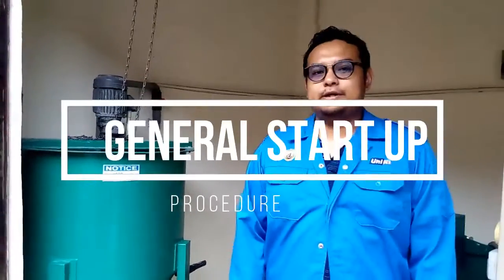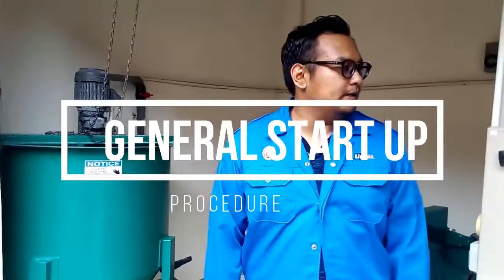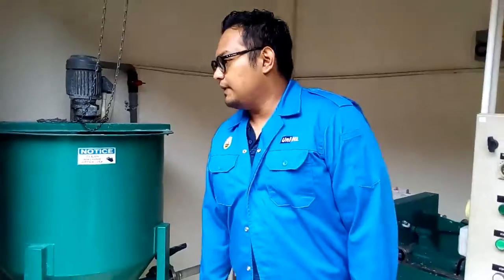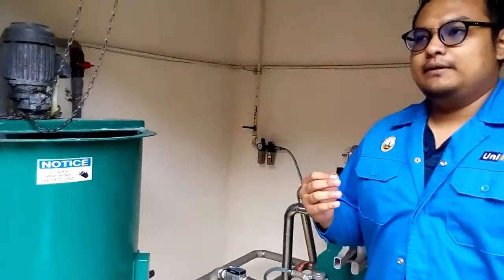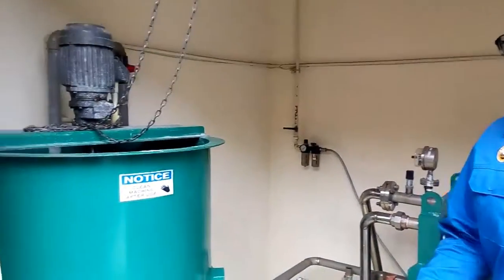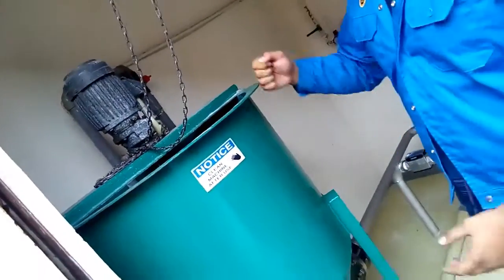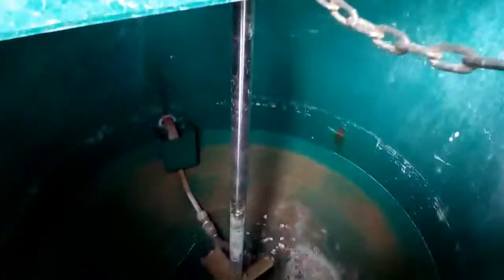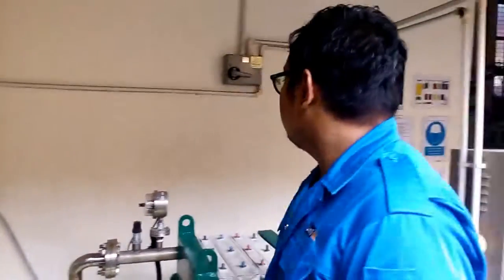Afternoon. Today I will explain about the general startup procedure in the leaching process or solid liquid extraction process. Firstly, we must mix 3 kg of calcium carbonate powder into 5 liters of water, and then transfer it to the slurry tank. After that, switch on the main pump.